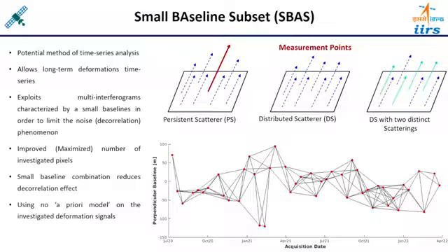So what happens? There will be a high level of coherence, or high level of similarity, between both the images of the corresponding pair. Suppose you are talking about a particular line, let us say this one, it means this image and this image, these signals are highly correlated. So in order to get high correlation between the signals, such a configuration was opted. Suppose 100 images are there, then they form the interferogram pairs with small baselines.